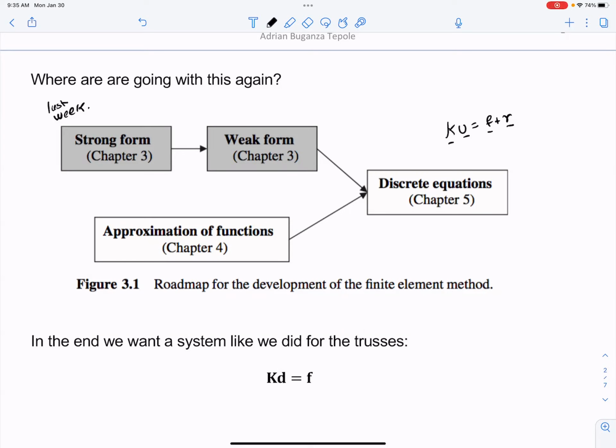The standard form of the equilibrium equation, the sum of forces equals 0, or the corresponding PDE, the way you solve it, usually you need to massage that expression a little bit into this thing that we call the weak form, which has some integrals, right? It might not make complete sense, but this is what FE solves.